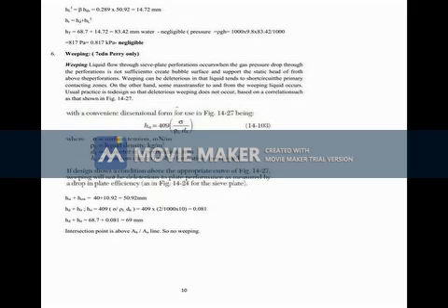Then next is HD is equal to K1 plus K2 into rho G by rho L, and UH is the velocity through the hole. Yesterday I explained the velocity through a tap in comparison with a shower. So UH is like a shower through the slots. It is coming as a shower, so the velocity will be more.